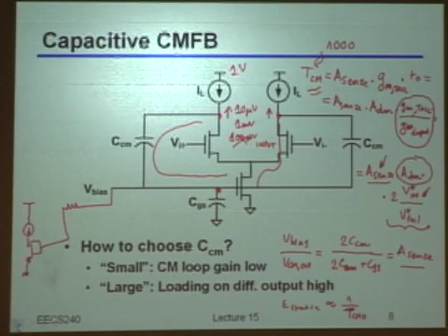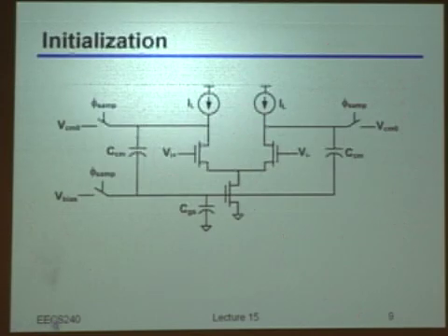So in this case, just because of biasing issues, you are also introducing CCM, and that happens to be really at the output. So indeed, for sure, you will have to implement some capacitor at the loading, like you're doing in your project, right? Just because of noise reasons. So you don't want the sample noise to be higher than a certain spec. But indeed, the idea is you don't want to also charge too much, to load too much, right? The differential stage.